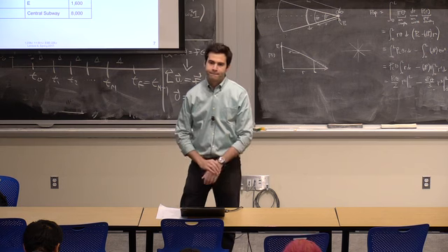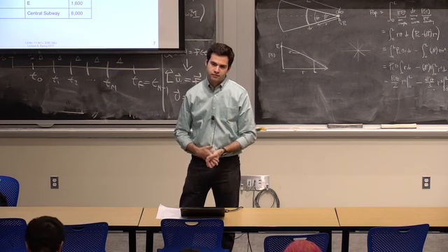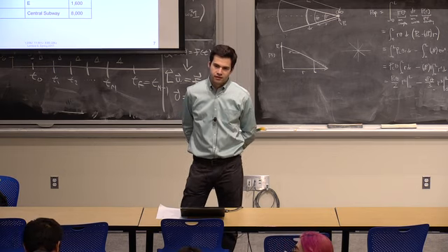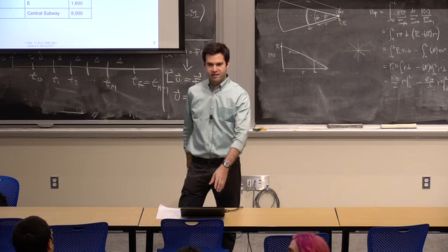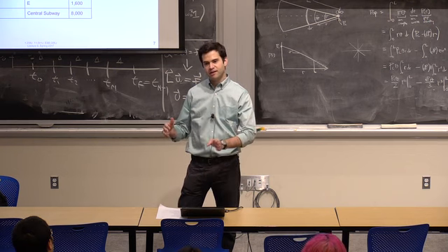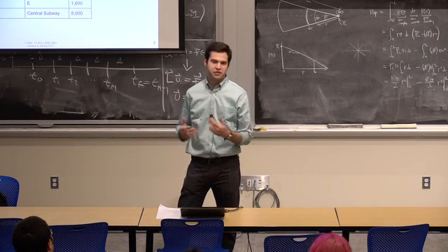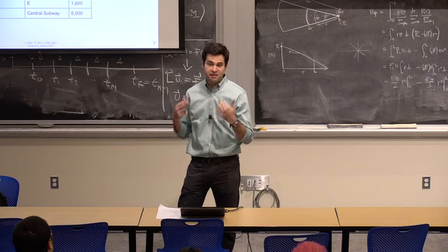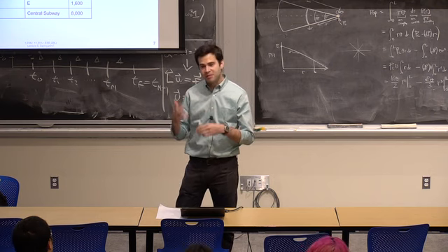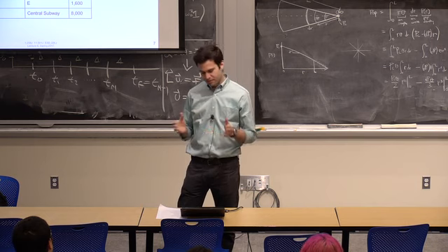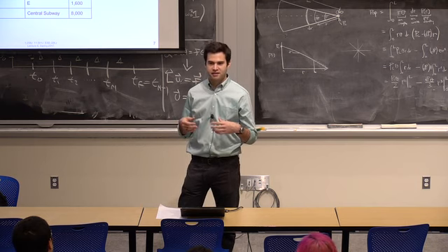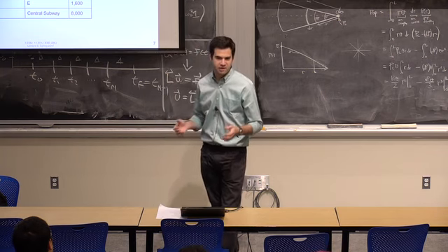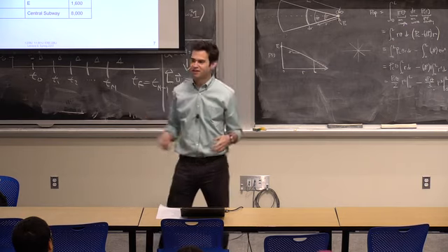We saw in a different course, one of the people from the T came, a graduate of the MST program, and showed slightly higher numbers than that. Yeah, so these numbers are a little dated. It depends on how you define the peak hour. And if I could show you the peak 15 minutes, that would be higher than this, for example. The peak of the peak is even higher than this. But it still is the case that these are not approaching the theoretical capacities, and that's because we don't have 2-minute headways and 10-car trains.